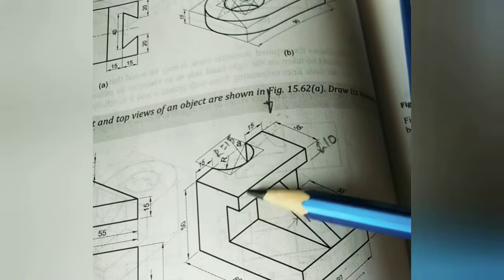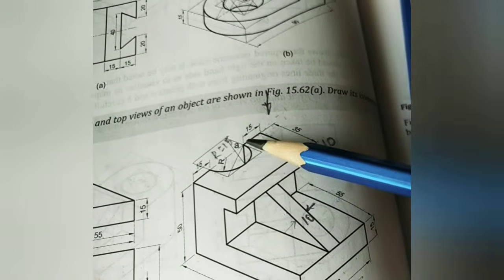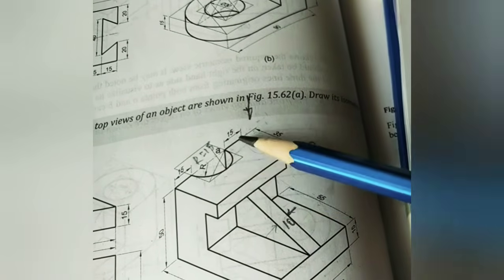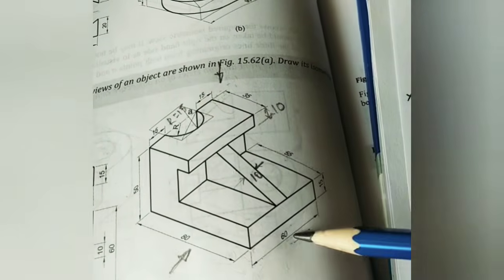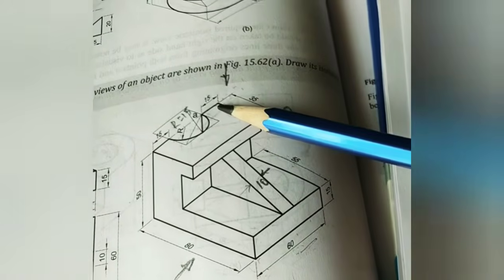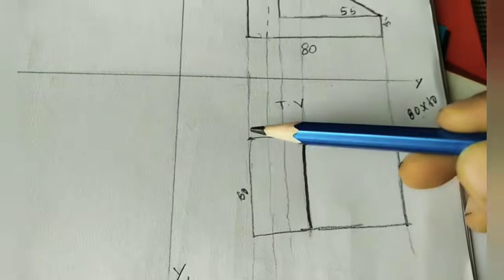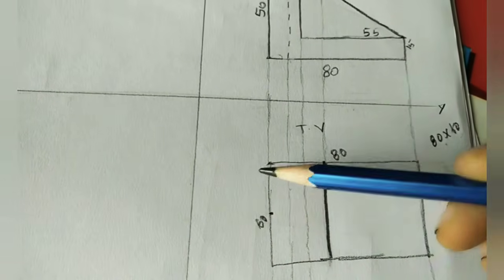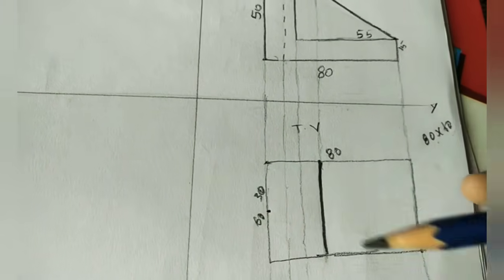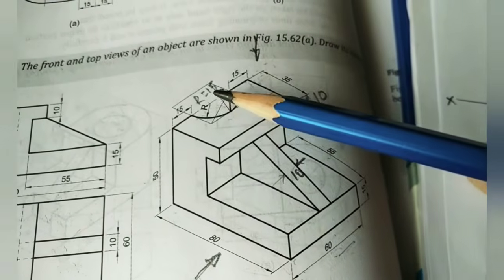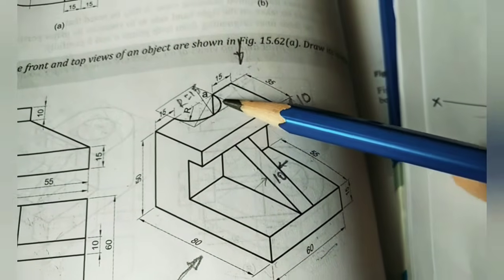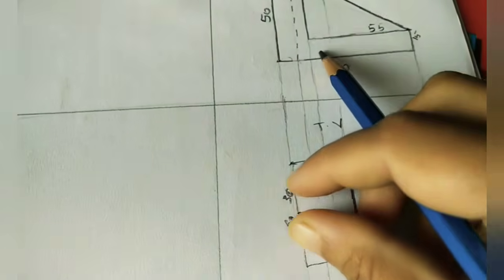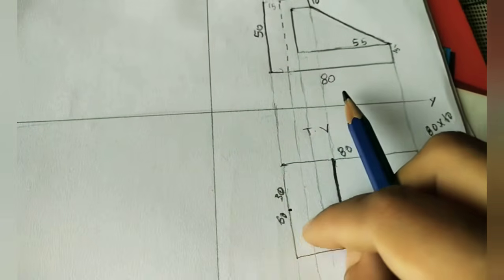In this rectangle this semicircular gap is there. We can see this semicircular shape from the top. Where it is a semicircle, at the middle of this 60 mm, we have to take 30 mm. So this is 60 mm, take the middle of it, which means here 30 mm. At 30 mm the center will come. So we can see the exact shape of the semicircle. Radius is 15 mm. By using a compass, take 15 mm and do the semicircle.